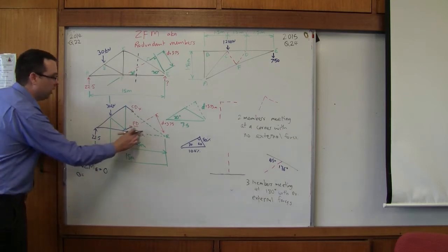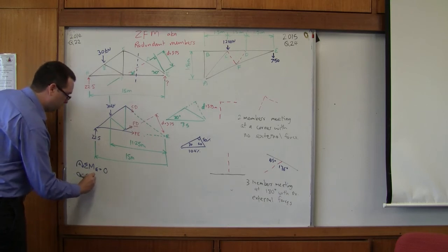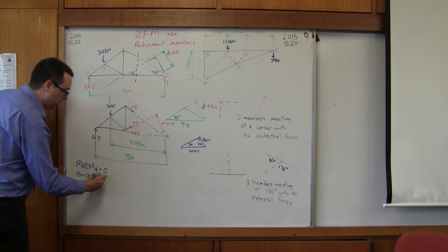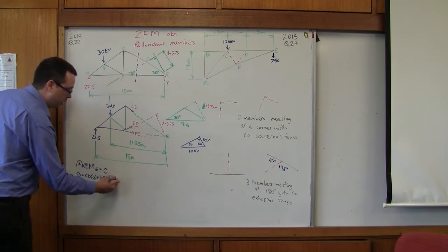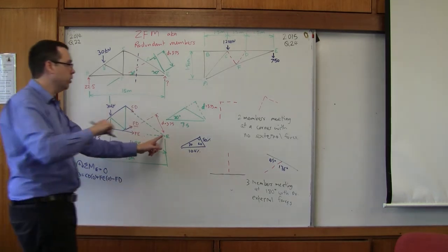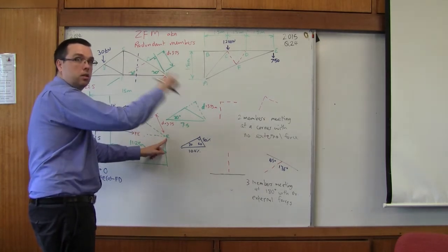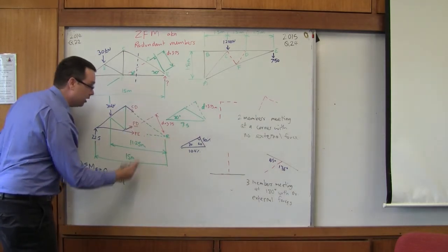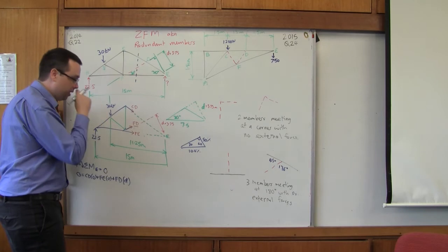So what we've got is, that X is confusing. Okay, so we've got CD multiplied by 0 plus, or generally it's minus, but it doesn't matter, FE multiplied by 0. Then we've got FD. Now, what did we assume for FD? Did we assume that it's positive? Is it clockwise or anti-clockwise? Let's put our finger on E and spin it. Positive, clockwise. Okay, and its distance is what we measured, D. And I could put that number in, but I want us to see where we're getting that value.